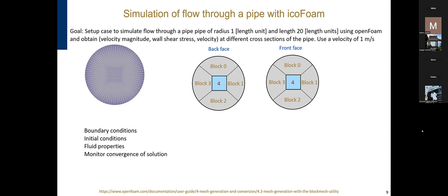We also have another variable, which is the pressure, right? So does this apply to the pressure? Yes. But in the case of the pressure, typically, because we don't even have an equation for pressure, what we have to do is we solve the Navier-Stokes equation, and then we use the continuity equation as the objective function. So you need to basically use that to constrain the pressure difference.